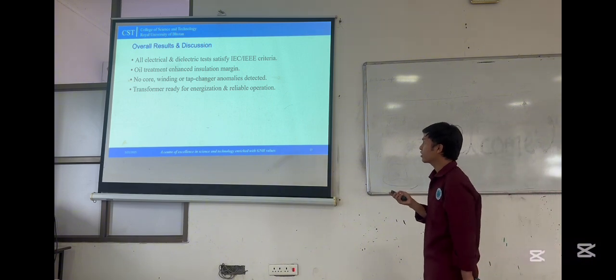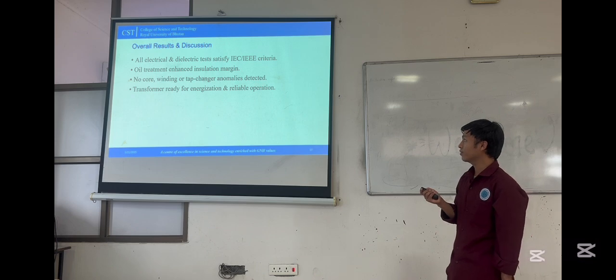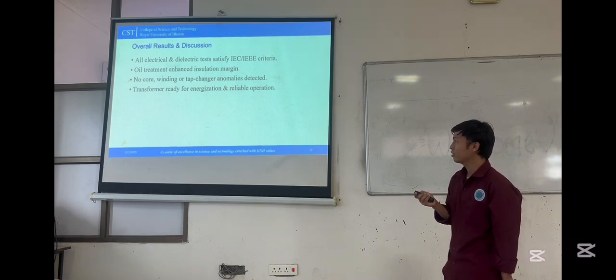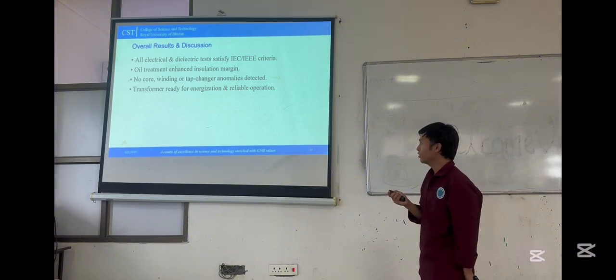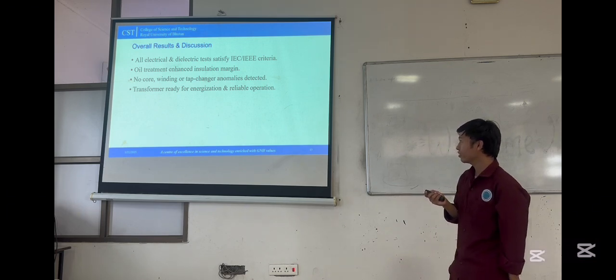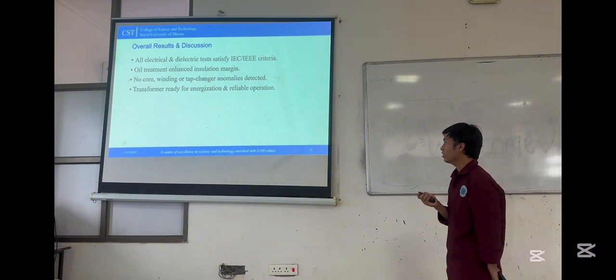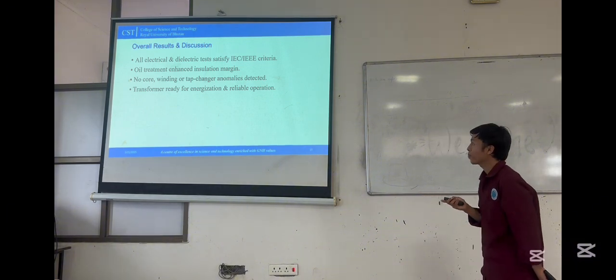Overall result and discussion: all electrical and dielectric tests satisfy IEC and IEEE criteria, and the oil treatment enhanced the insulation margins, with no core, winding or tap changer anomalies detected. The transformer is ready for energization and reliable operation.